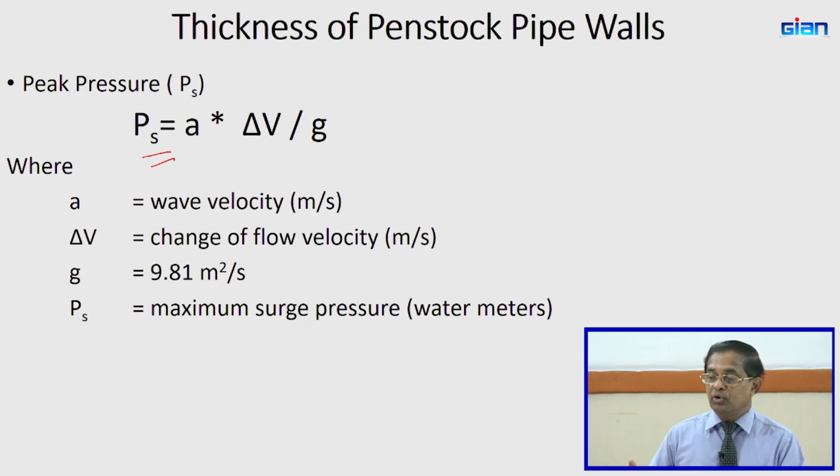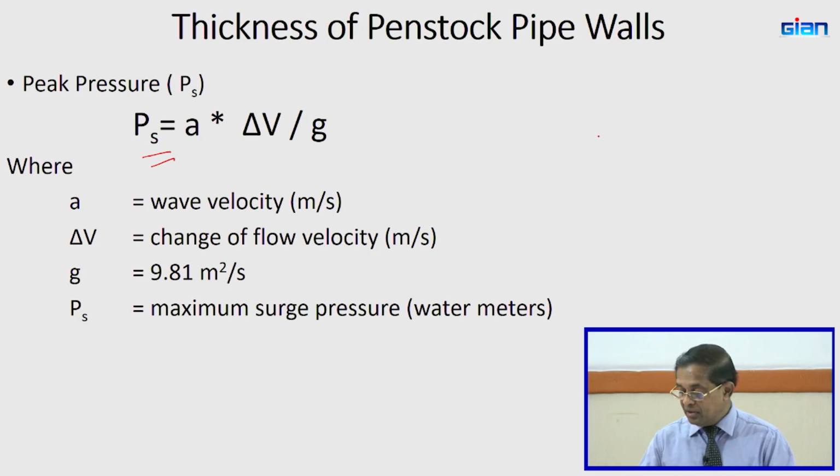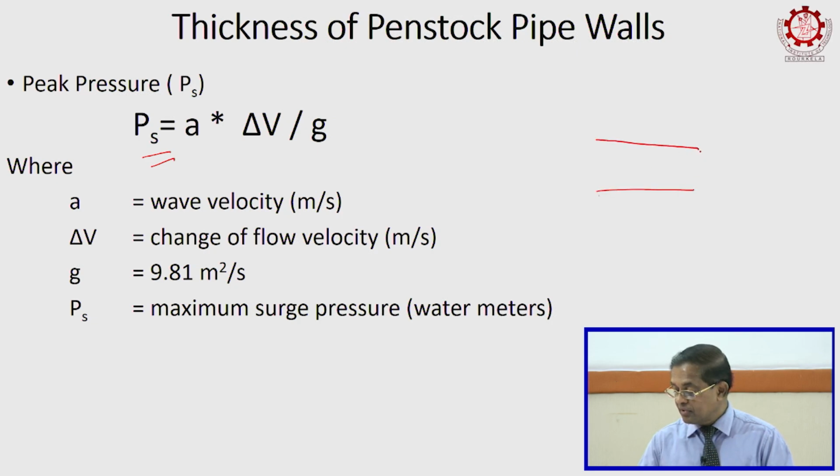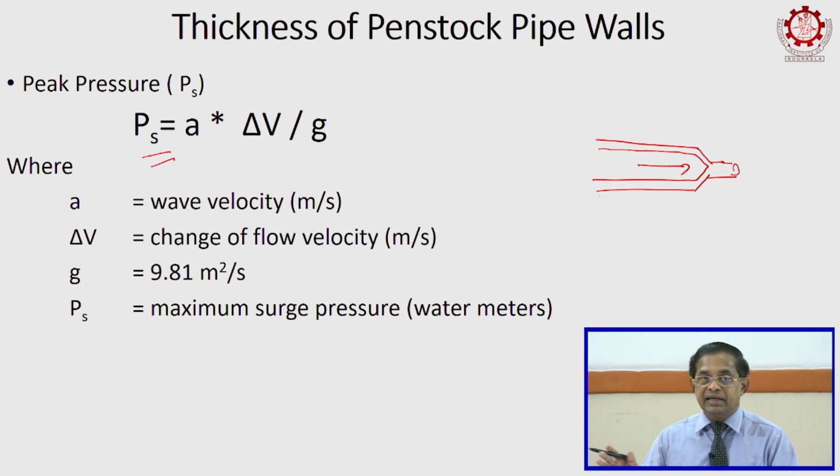That is the possibility, because if you have this final water jet, your needle valve will be like this. From here you will have a needle moving up and down to close and open the final water jet hitting the turbine.